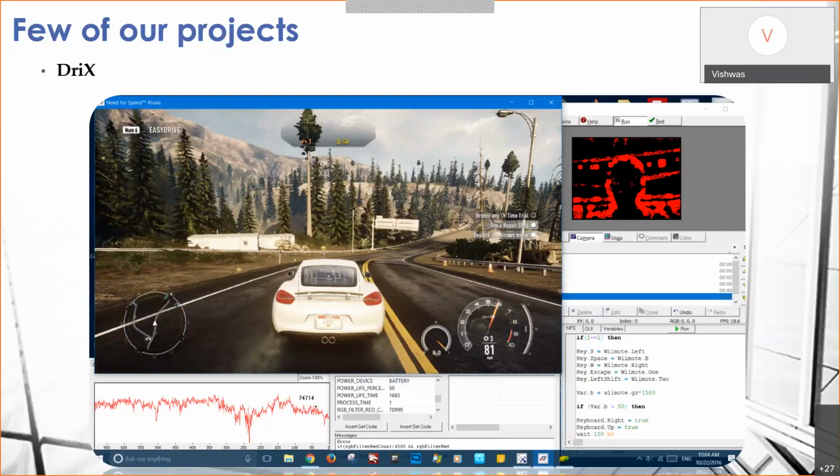So these are very important features. Most of the accidents happen due to human error, or falling asleep, or something like that. In the top right, you can see there is image processing going on. This is the driver's eye closure being recorded. Using certain image processing algorithms, we are using a camera-based vision system, so it will directly detect the eye closure of the driver. If it is closed for a certain period of time, we will stop the car. Here, through the Need for Speed game simulation, we are just showing how the whole process happens and how the car will be stopped.